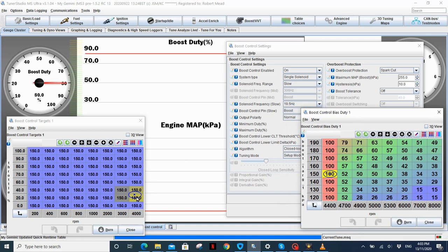And you can see we're down here with the throttle position. We'll just turn it up for the sake of it. Actually, we can change these values here, and let's say 180, and then you'll see, have a look over on the right at the boost, the bias table, and you'll see it move up there.